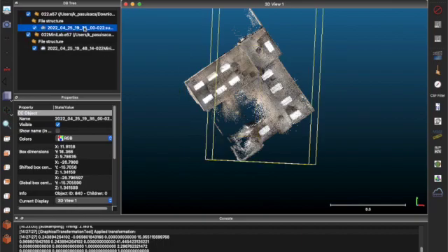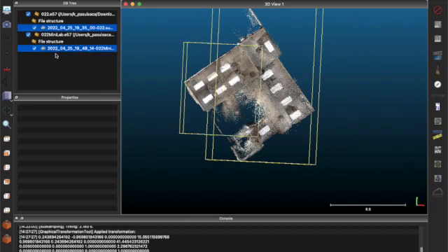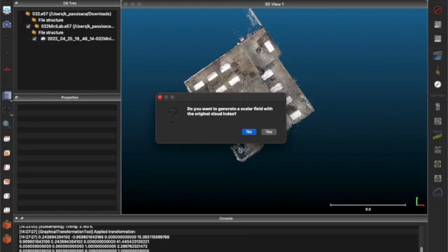So keep in mind that the first file that you select to merge will be the name of the file of all of the scans merged. So I went and clicked on the 022 file first, and I'm gonna click on the other scan and click this tool, the merge multiple clouds. Once you merge them, it's merged. You can't go back. You have to start over. So that's why you want to make sure your files are really aligned.